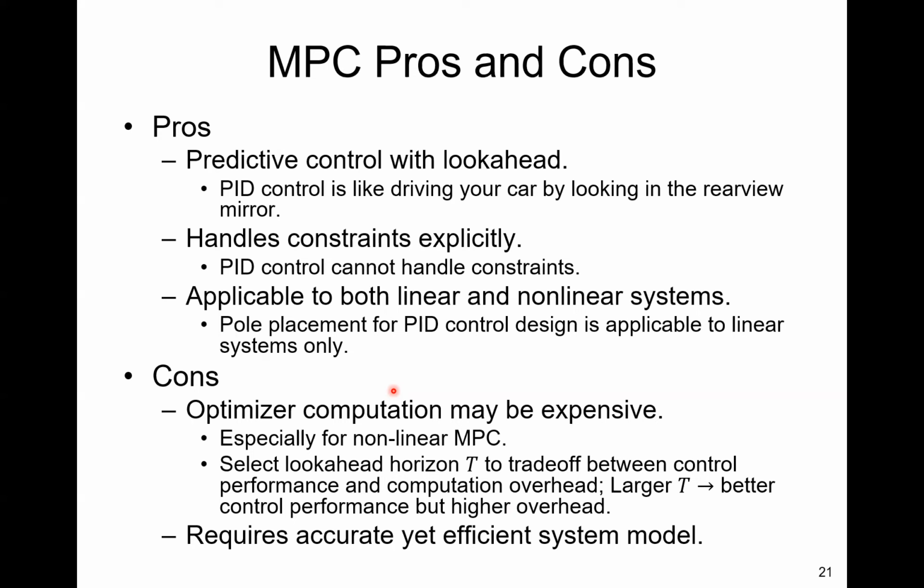But when you apply it to automotive control, the time horizon becomes milliseconds. If you want to control your actuators 30 times per second, at 30 hertz, then you only have 33 milliseconds to compute a command. So by moving MPC from a very slow scenario in factories to a very fast application scenario in cars, there has been a lot of research on making MPC faster.